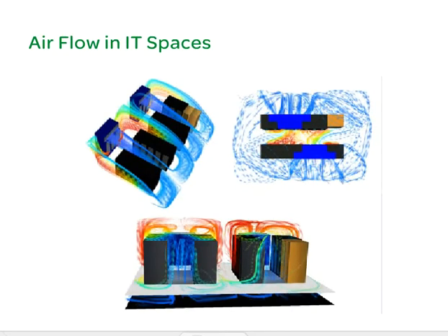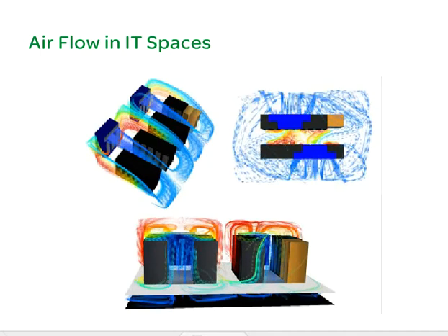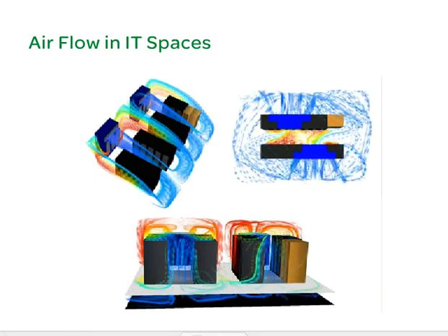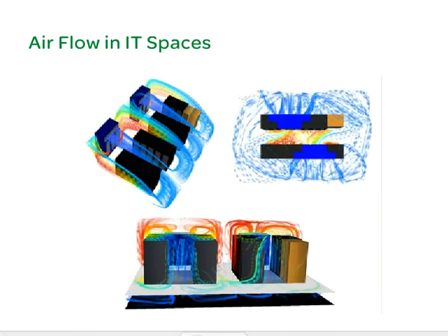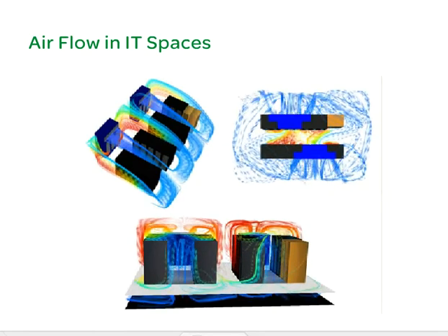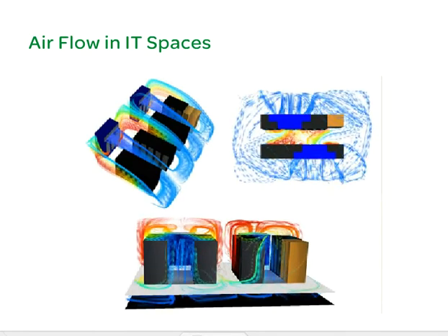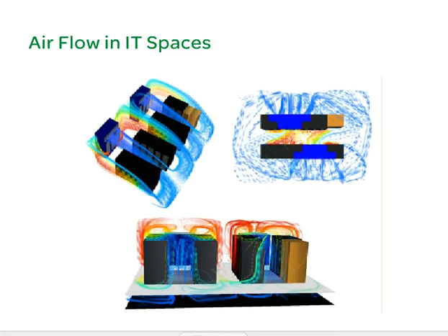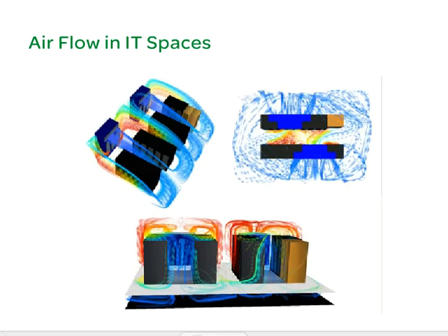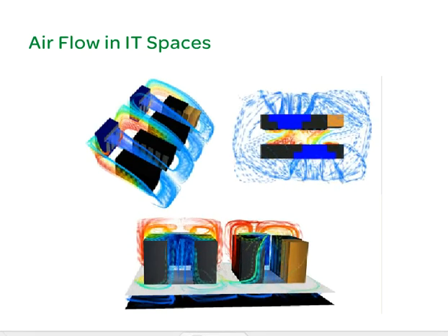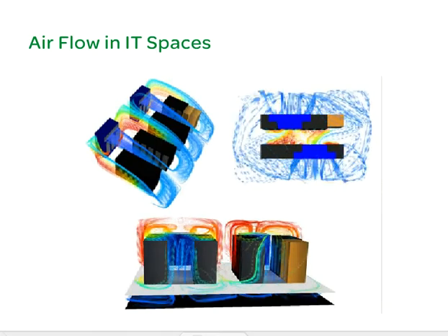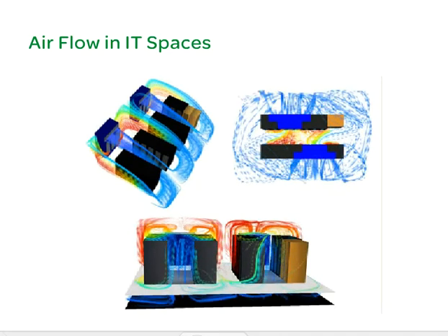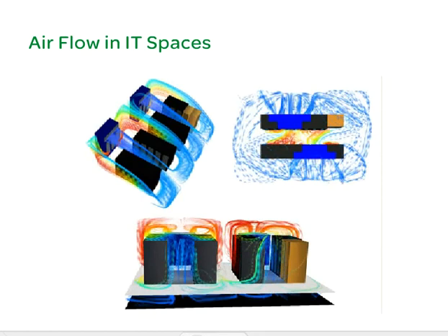As mentioned earlier, heat energy can only flow from hot to cold. For this reason, we have air conditioners and refrigerators. They use electrical or mechanical energy to pump heat energy from one place to another, and are even capable of pumping heat from a cooler space to a warmer space. The ability to pump heat to the outdoors, even when it is hotter outside than it is in the data center, is a critical function that allows high-power computing equipment to operate in an enclosed space. Understanding how this is possible is the foundation to understanding the design and operation of cooling systems for IT installations.